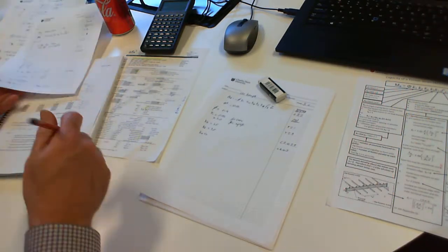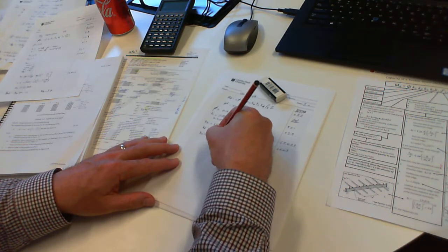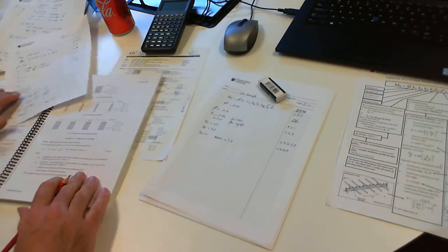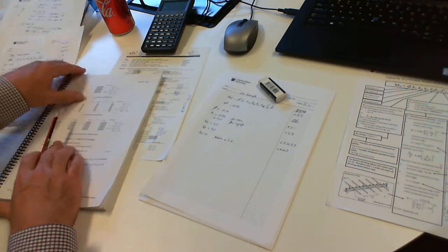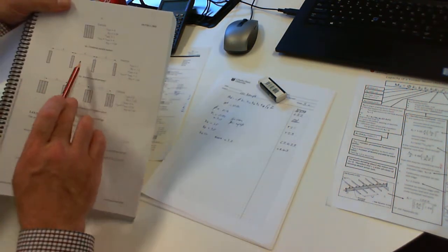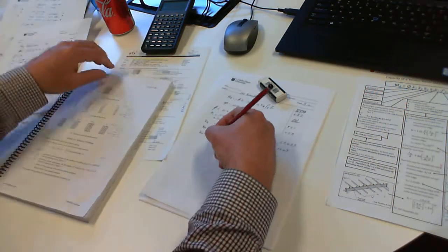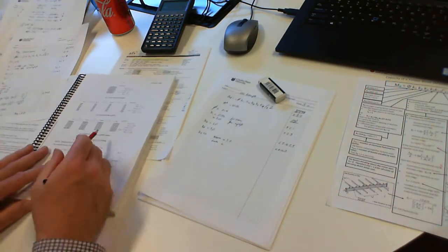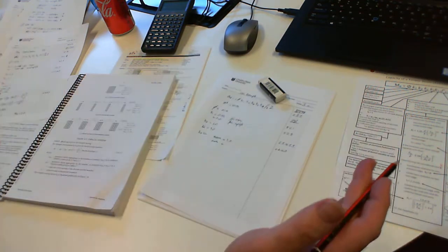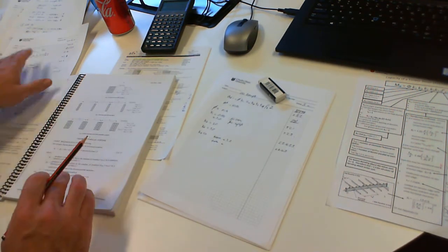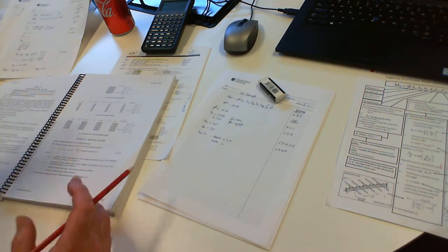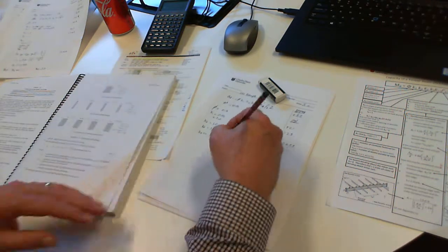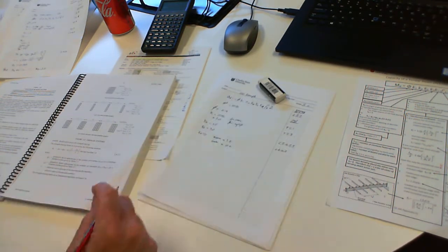Now in this case, NCOM equals 1.0, or 1 really. How many of these beams are together? None of them nailed together. It's an individual beam. NCOM equals 1. NMEM, which is the number of members acting in parallel, says, alright, how many of these beams are lined up across this roof? Now, to be fair, I haven't told you that. I've just said there's a large number of beams. Now the table maxes out at 10, so we'll take 10 or more. So we'll go 10 plus.